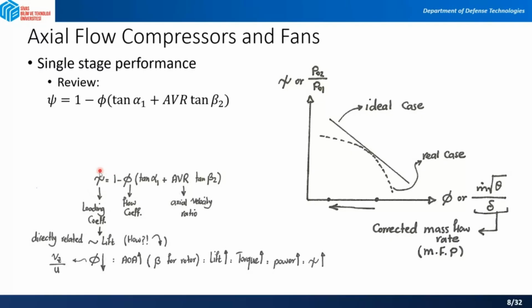And this loading coefficient, this question might come to your mind: why do we call this the loading coefficient? What does loading mean? Because you remember that when you have an airfoil, when you have lift, the load on the airfoil is the lift force, right? So the loading coefficient is directly related to the lift. And in here, we show how it is directly related to the lift.